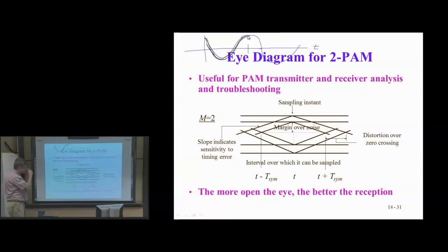The same thing holds with the eye diagram. If I use a pulse shape like the truncated sinc or raised cosine, or square root raised cosine for that matter, then over that period the pulse shape looks like this in a non-causal plot.